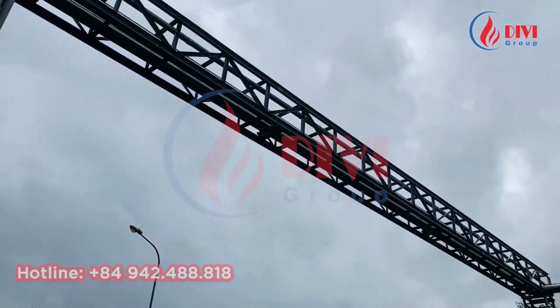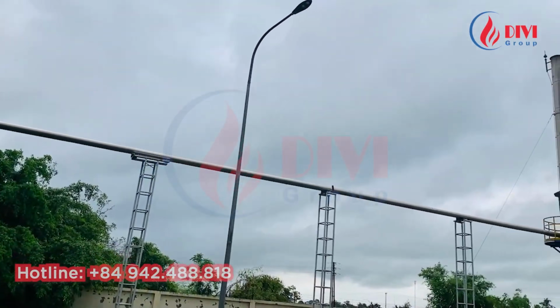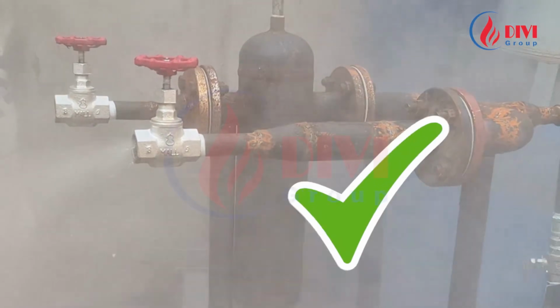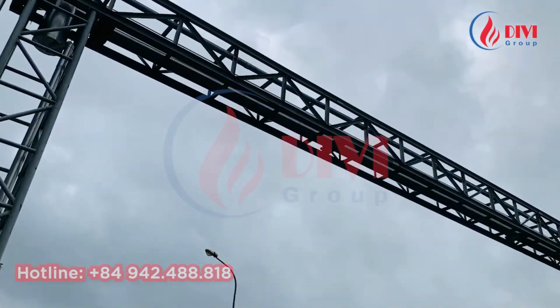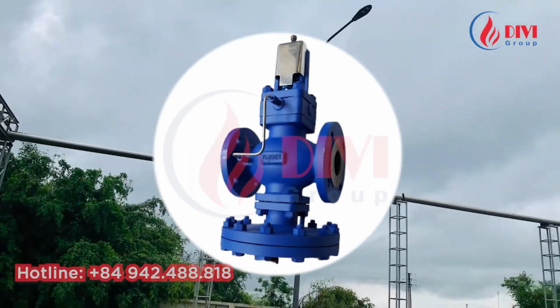Conversely, if you have steam pipelines longer than 50 meters, or if the steam must pass through pressure-reducing valves or regulating valves before entering factory equipment, installing a steam separator is fully justified to protect these valves. A steam separator helps the valves operate more stably and reliably, preventing damage caused by water hammer.